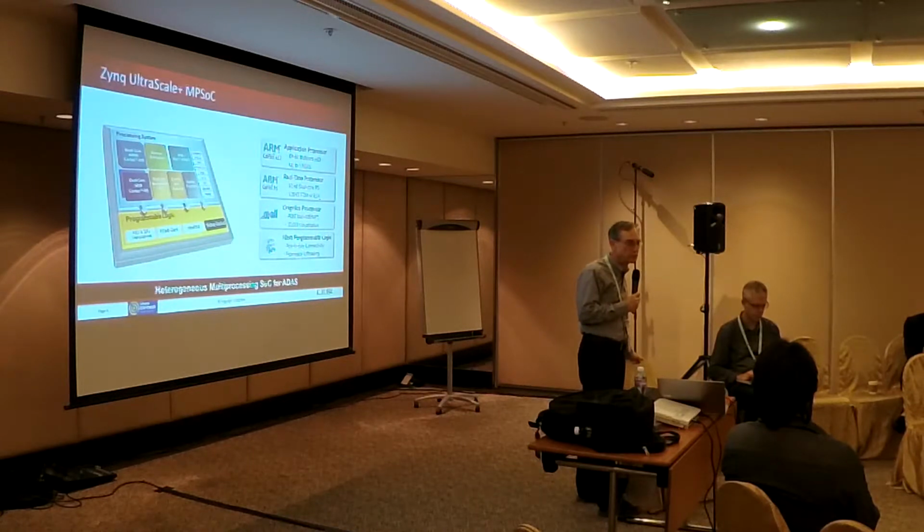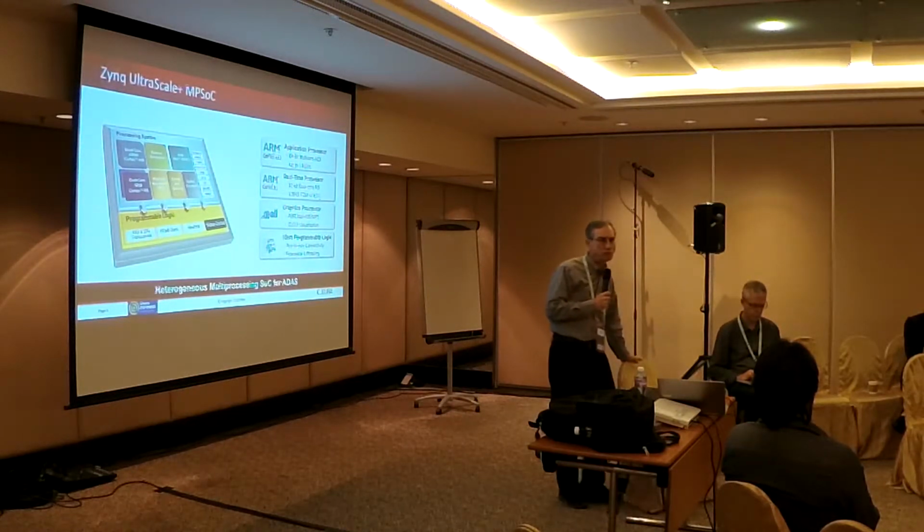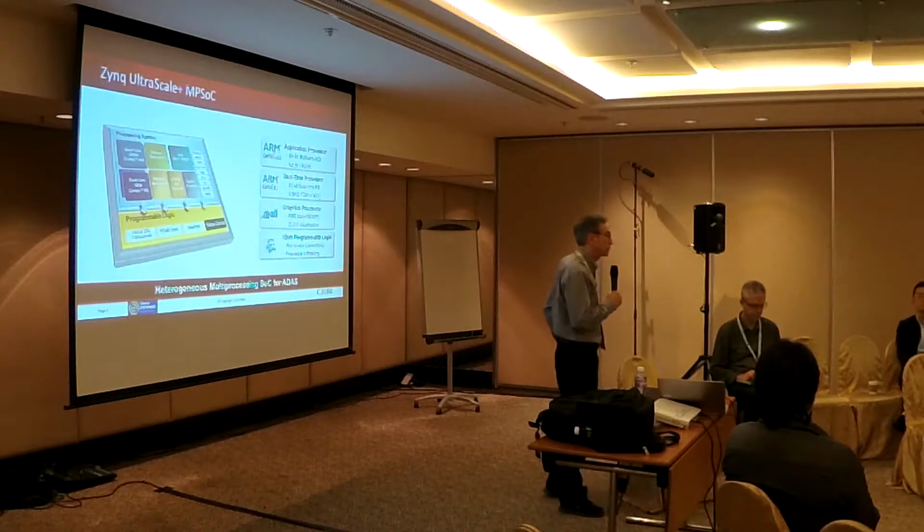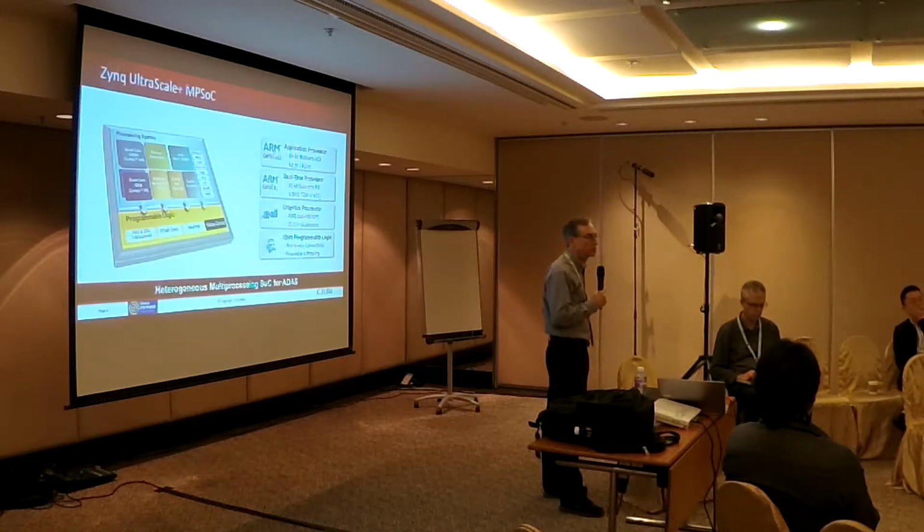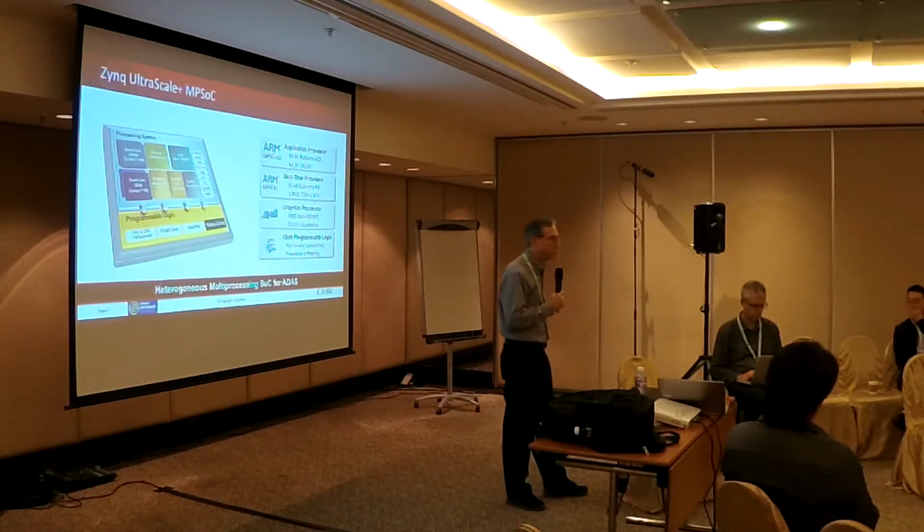It takes about an hour, but you have probably all heard about radiation. Radiation can strike a memory cell and cause a bit to flip in that memory cell. Most of the time, when we're talking about our PCs at home, our laptops, etc., we don't worry that much about it because the probability of it happening on your particular unit is extremely low. It may take years before you have a single event upset that is likely to disturb something you are doing.